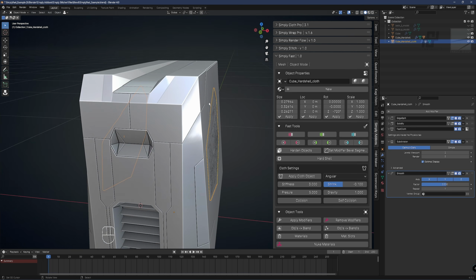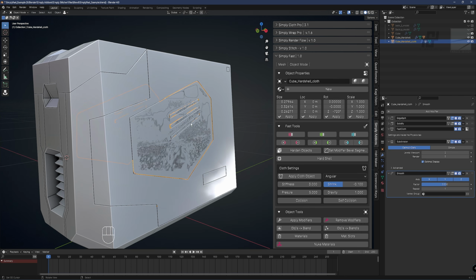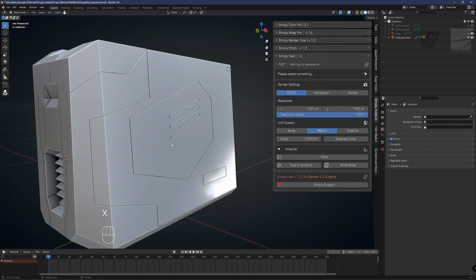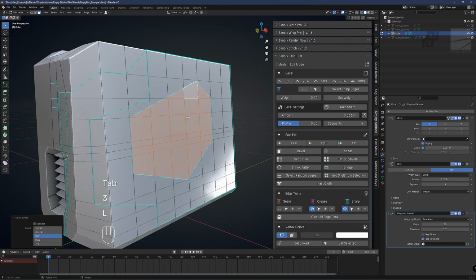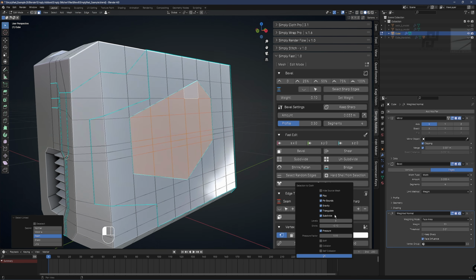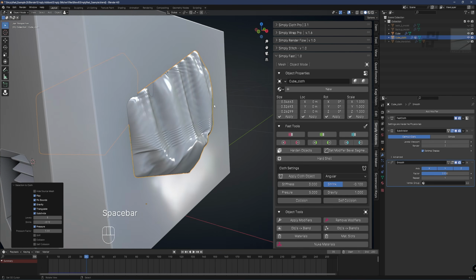So hard shell, we create a subdivision, solidify modifier, which are creating the object inside and outside. So we need to understand not to create fast cloth here. So this was the point. If we go over here and select only this part, and now making the cloth with this desired look, it will only make it outside. So it has one object, you see this, it's great, a bit of strange shading depending on the topology.